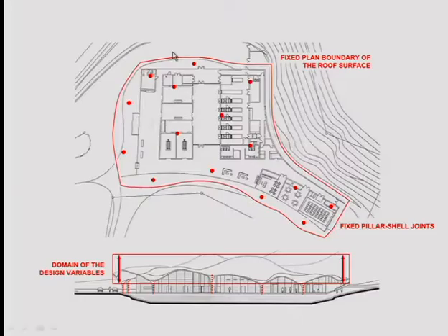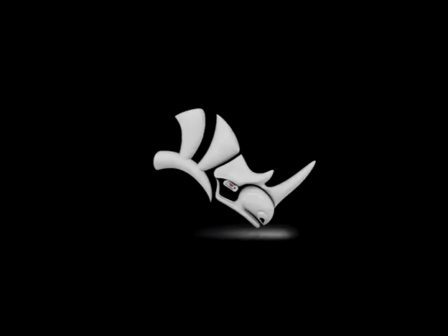So what I'll do, I'll define boundary conditions. Remember we talked before about boundary conditions. So boundary conditions are the columns, the position of the columns, and the height of the columns. But if I want to understand which one is the best shape, I have to tell the computer among which set of candidates. So I have to say, for instance, I'd like to move just the z coordinates of the points, and maybe let's say between 3 to 10 meters height. So I need to provide a variety. All right? Let me show you that straight away in Rhino.